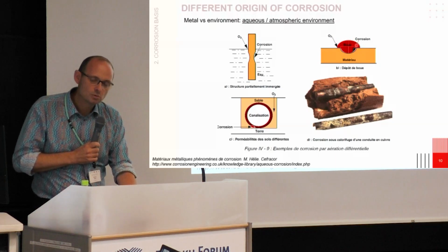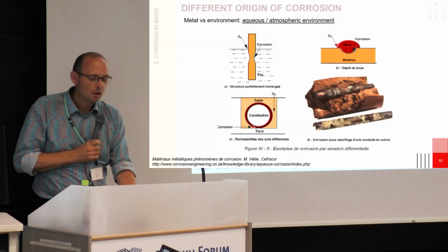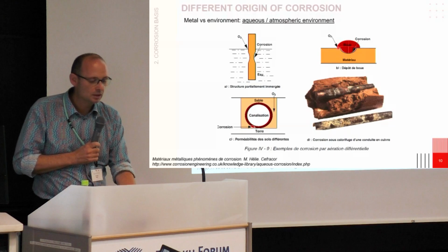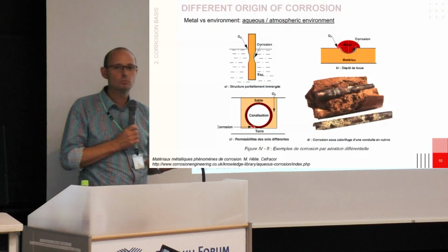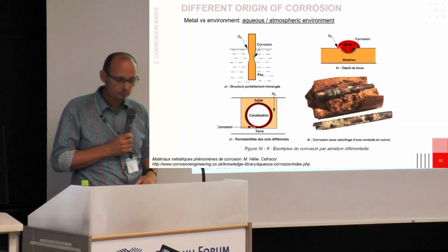It also diffuses slowly in the solution, but because there is a lot of oxygen available here, if corrosion occurs, electrons of iron are released here, the electrons move here, and react at the boundary of the droplet, where the oxygen is available.